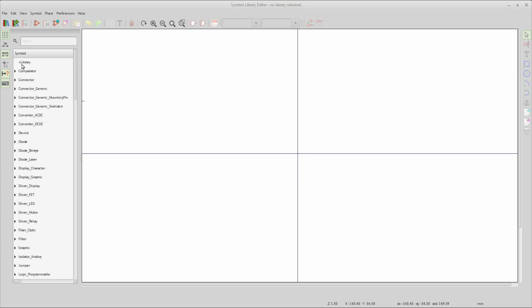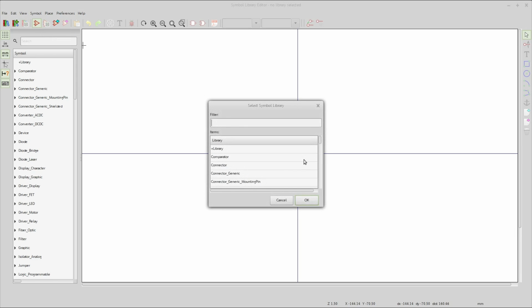And then you see what I'm talking about right here? Plus sign libraries. It alphabetized. Otherwise, we'd be scrolling down to my libraries every single time. All right, libraries is there. It doesn't have a little arrow next to it because there's nothing in it yet. So now we can create a new symbol, and we pick the library right there because that's where we're going to do it, and hit OK.